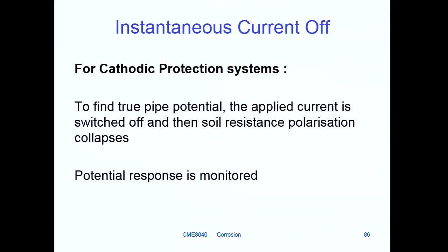It's a sort of related thing. I just wanted to mention instantaneous current off measurements, which are used to identify the true pipe potential by correcting for the IR drop, the polarization resistance that you get because the soil isn't very conductive. And I think that was your last slide.